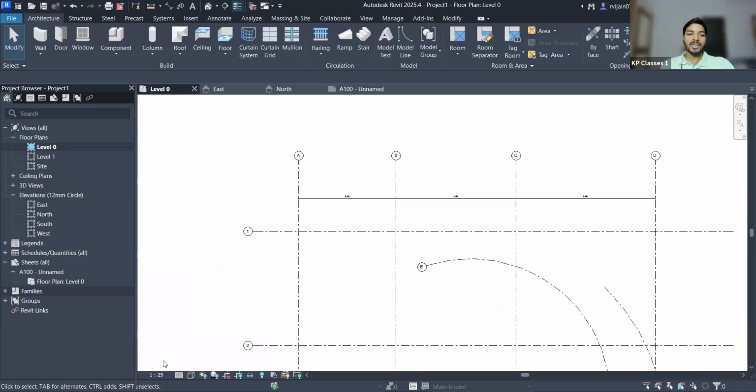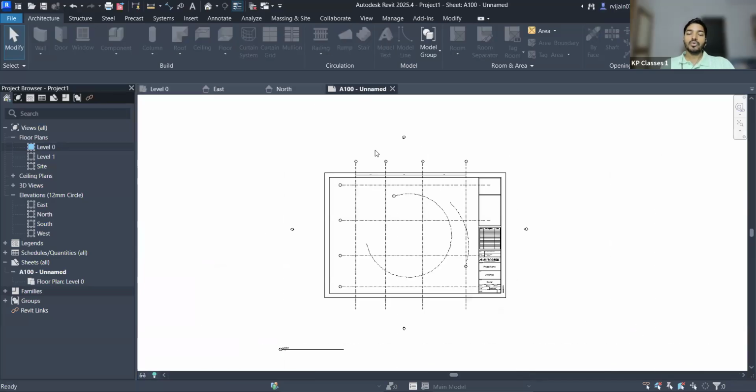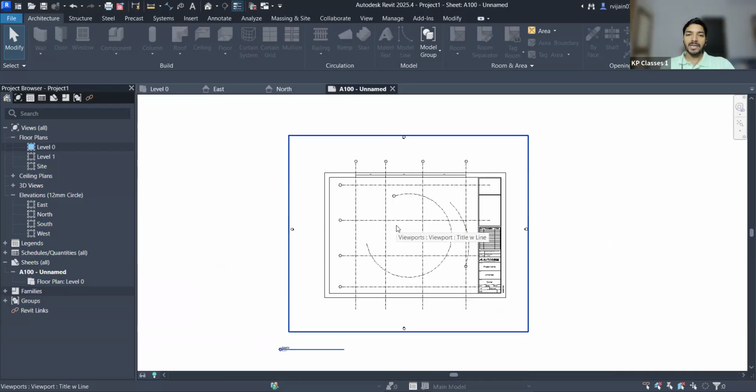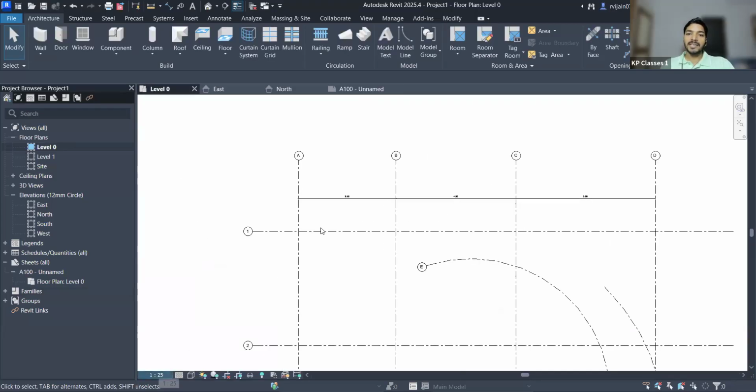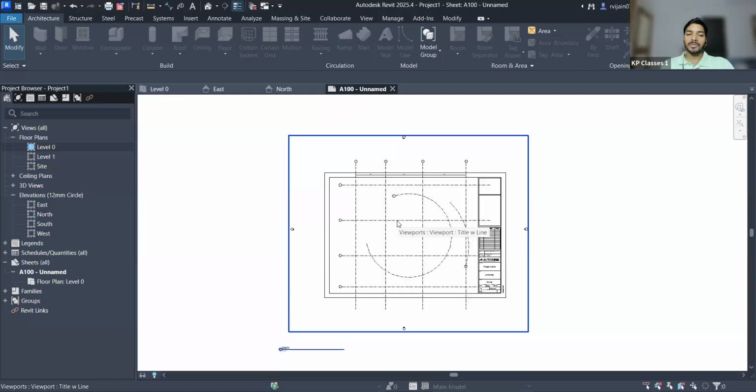For better working, you can definitely change the scale, but to have it fit feasibly on the sheet, you have to ensure that you are choosing the correct scale. Otherwise, for working you can have another scale, but that will not necessarily get your information fitted on the sheet as well. So changing the scale for working is temporary, but changing the scale to have your information on the drawing is more important.